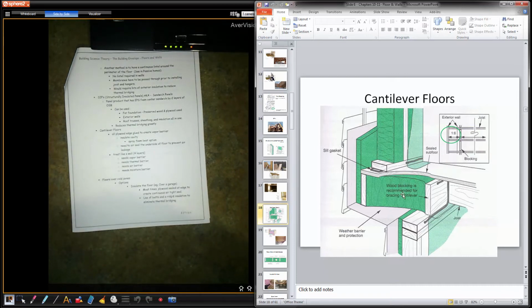That's a floor. So the R value in a floor is going to probably be closer to an R30. Again, if you check SB12, depending on the package, that number might change. But I believe R30 is a pretty constant number for insulated floors. So not as much as a ceiling, but more than a wall. Again, a lot of people will put a layer of styrofoam underneath here, which helps with air leakage, helps with thermal bridging. Okay, so vapor, thermal, some kind of a barrier here to create the air and the moisture.